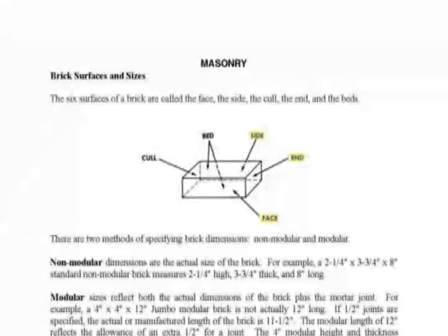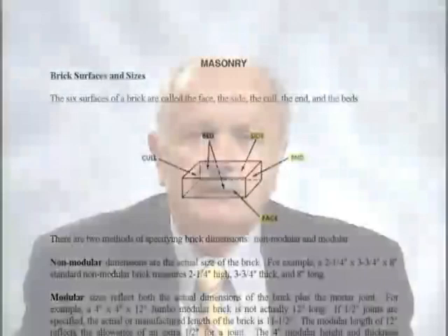And then let's get into mortar and grout. Mortar and grout. Understand the difference between the two. Grout is what's poured into the cells of a concrete masonry unit or a concrete block. And it is also poured between 2 brick walls. And those 2 brick walls are technically called widths. You'll see that in the next couple of pages here. Grout is hidden.